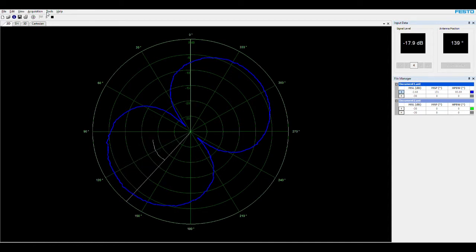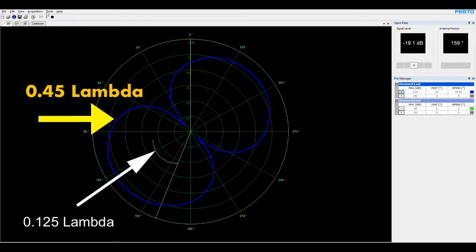So as you see, we are maybe about 16 or 17 dB down from the other one. Now when the acquisition is complete, we can have a better guess. It's a little bit not symmetrical yet. The other side is bigger, so we could look into that and see. Remember, the antenna is symmetric, but other things could be the problem.